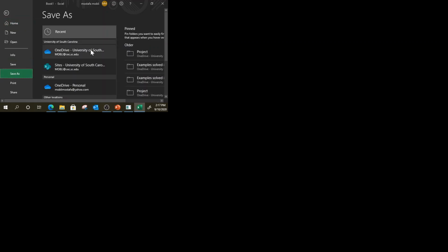Then you save this as a text file. That's very important. It should be a text file in your Xfoil folder. Text MS-DOS.